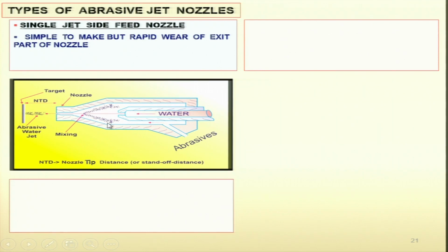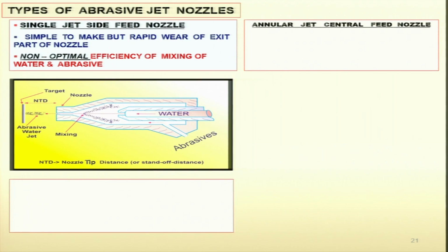It is simple to make, but rapid wear of exit part of nozzle. Here, because abrasive particles are hitting the nozzle, the wear of the nozzle takes place faster. Non-optimal efficiency of mixing of water and abrasive. Mixing is non-optimal in this particular case.